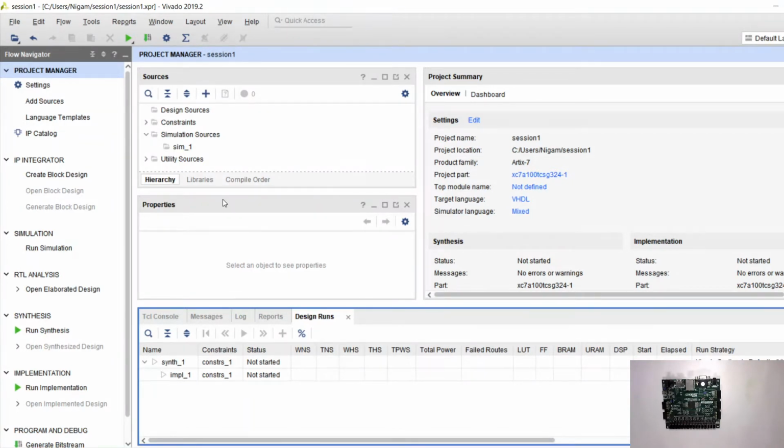Or for example, you want to use a bus architecture, which is let's say an AXI bus, right? Or an AMBA. AXI is basically an evolved form of AMBA, an on-chip bus for ARM processors, right? So that IP can be included, right? So for example, USART, UART, and all that, right? Controllers, you don't have to write VHDL code. They are available as IPs, and you can build the circuit around those IPs, right? So that's there.